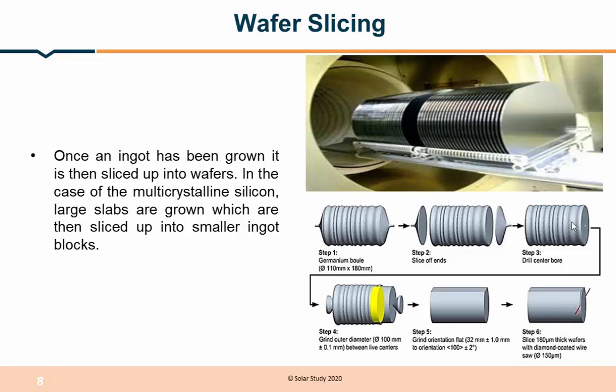Then it grinds the outer surface to make a very clear, thin surface, because in this image you can see the outer boundary is not clear; it is zigzag. Inside the chamber, they polish the surface and make a very flat layer on the outside. While grinding, we generally call it surface grinding, to make the outer side of the ingot smooth.